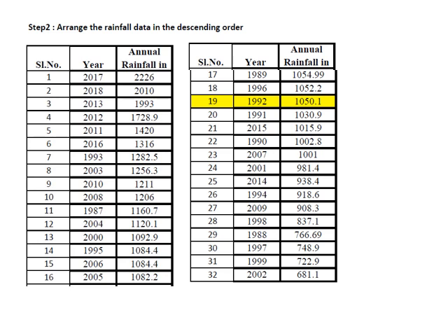That's the reason why we go for what is known as a dependable rainfall, and then decide the storage volume. For that storage volume, we go for the design of the bund after fixing the normal reservoir level as well as the maximum water level.